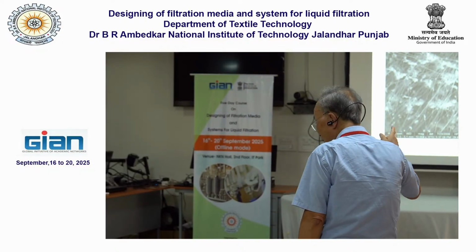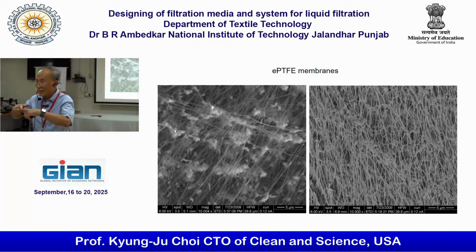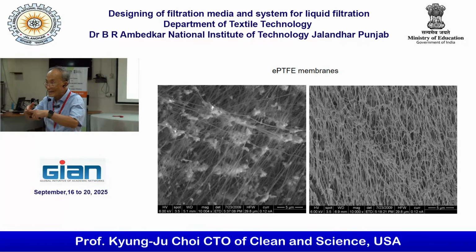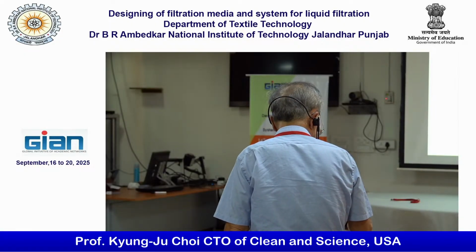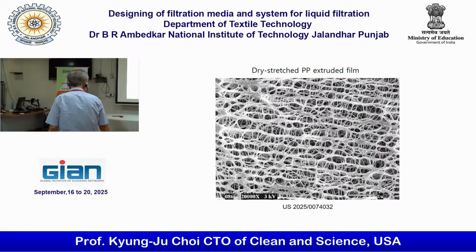Somehow you have to understand the fibers are not bonding to each other. So it's one on top of the other. So porosity is more than 90%, 95%, something like this. However, in that one, the fiber is not stretched like this. That's why the porosity is a lot lower. But however, that is in the 1 micron range. So the individual fibers inside are quite small.